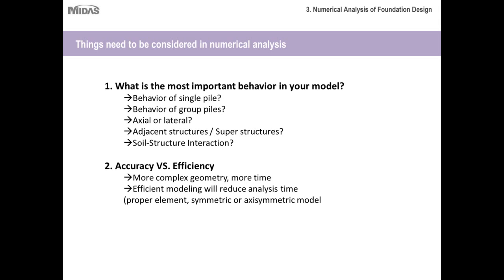So the questions go something like this: what is the most important behavior in your model? Ask yourself whether it is the behavior of a single pile that is of prime interest to you, or the behavior of the pile group, or whether there is a very high axial or lateral load onto the pile, or an adjacent structure or superstructure that you have to consider, and how complex the soil structure interaction will be in this soil strata.